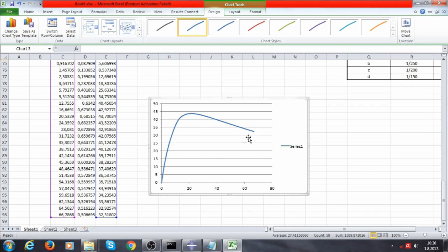This is exactly the way we would expect our load displacement curve to look like. We can see that the peak value is around 44 kilonewtons. You can use your engineering codes to calculate the ultimate load and compare it to this one. I think this is a bit higher value than I've calculated using Eurocode, but that's pretty normal because codes are usually a bit conservative.